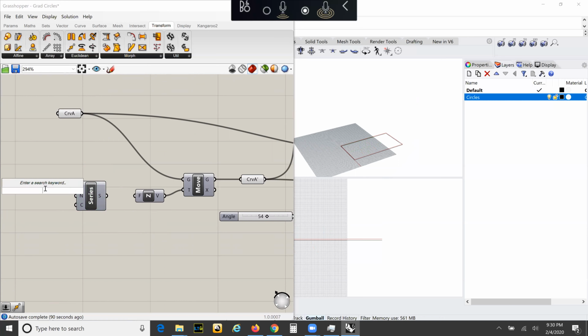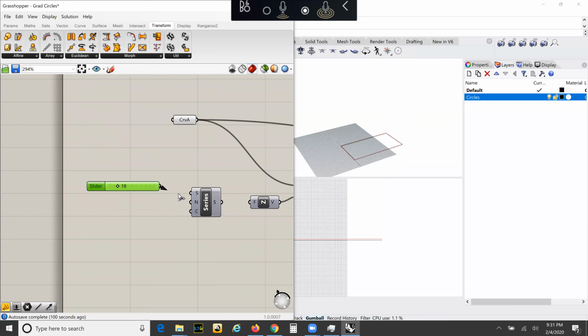We're actually going to start at 18. 18 is a pretty healthy amount. And why we start at 18 is, a lot of times for architecture, the retail space, which is on the lower floor, wants more ceiling height. Because with higher ceilings, studies have shown that retail is more successful. Also, they're more flexible if it wants to be a restaurant or a coffee shop. So we're going to start off at 18.